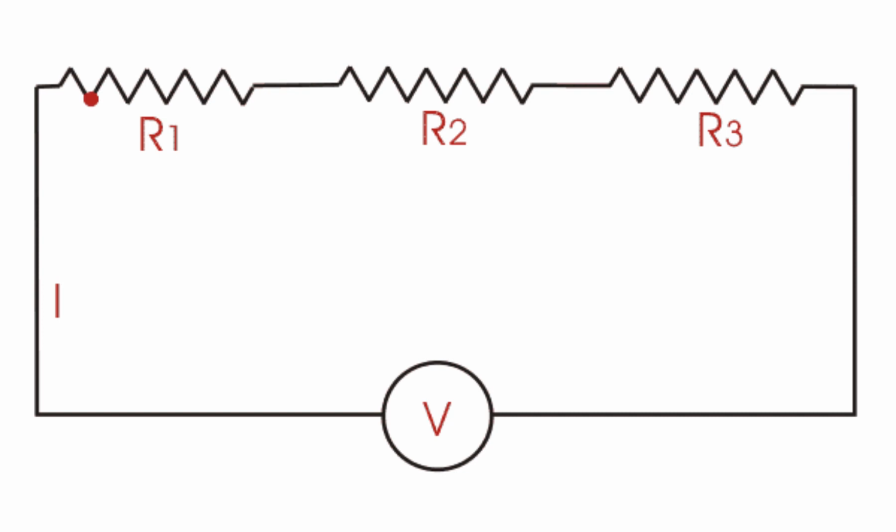Voltage dividers. One common use for series circuits is the construction of voltage dividers. A voltage divider works on the principle that the sum of the voltage drops across a series circuit must equal the applied voltage. Voltage dividers are used to provide different voltages between certain points. Voltage dividers can be constructed to produce any voltage desired.